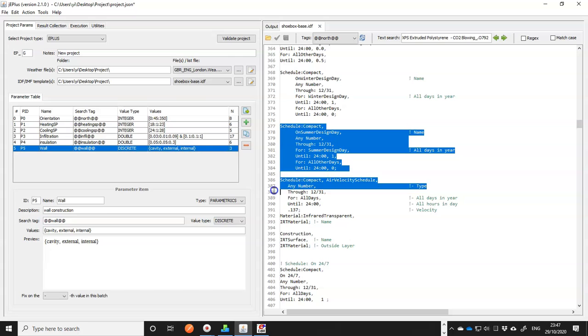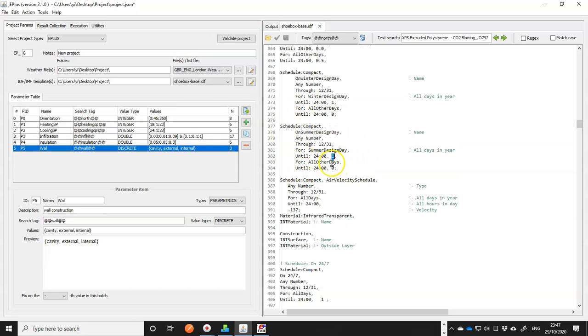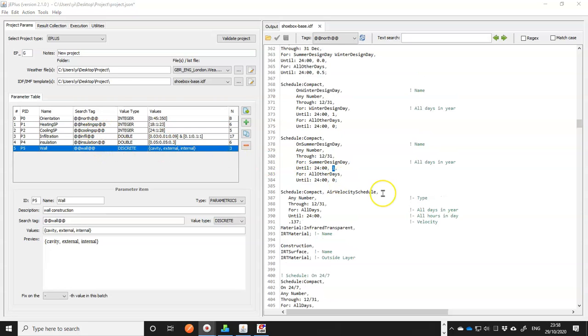You can have as many schedule objects in your model as you like, and use a parameter to control which one is actually used. And of course, you can change the field within each schedule object, like what we did with heating and cooling set points. Next, let's look at the geometries. Shading first.